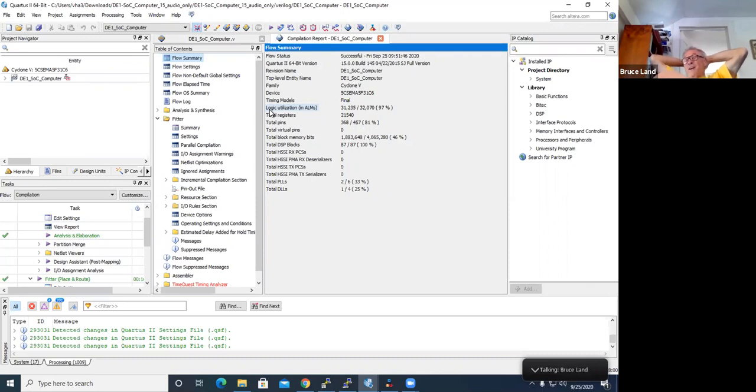But you can always serialize the multiplier and use it over and over again, just like a regular CPU does, just like the ARM9 uses the same multiplier over and over again, as long as you store the results someplace, hence the memory. So the number of multipliers will limit how many nodes you can update simultaneously in parallel.